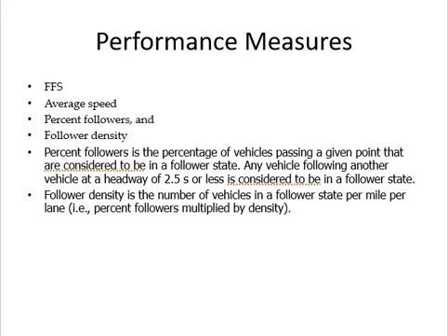How close is considered a follower? If the headway between the two vehicles is 2.5 seconds or less, this comes under the category of a follower. This is a very small time window, right? Somebody applies the brake, and you don't have enough time to do something else. First of all, you have to slow down. Later on, you may get the chance to pass and do other things. So a person with this much headway is considered a follower.